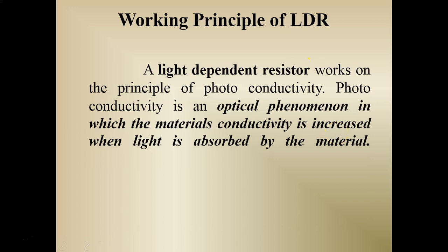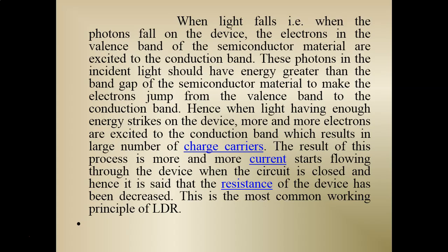Principle. It works on the principle of photoconductivity. Photoconductivity is an optical phenomenon in which the material's conductivity is increased when light is absorbed by the material. When photons fall on the device, the electrons in the valence band of the semiconductor material are excited to the conduction band.